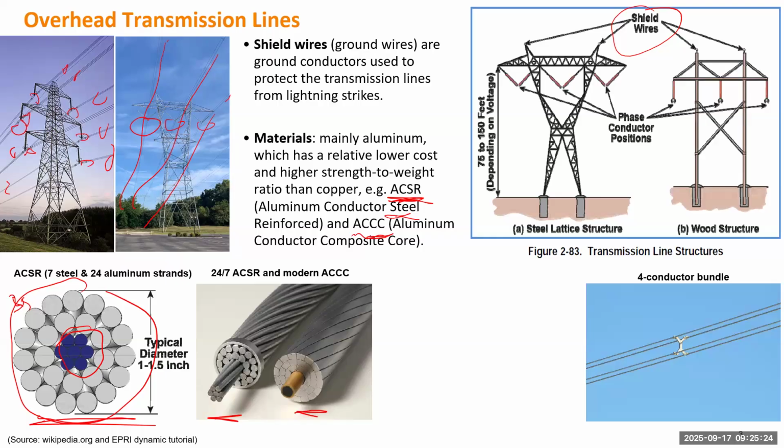But when you look at an even higher voltage line, even in this picture, if you look more closely, in each phase there's not just a single straight line, there are multiple ones. That's because of this design. When you operate at even higher voltage, you can either make a very large conductor, which will have more corona effect, so you have more shunt conductance, or you can split the conductor into maybe 4 smaller conductors, with a short circuit connection between all the 4.